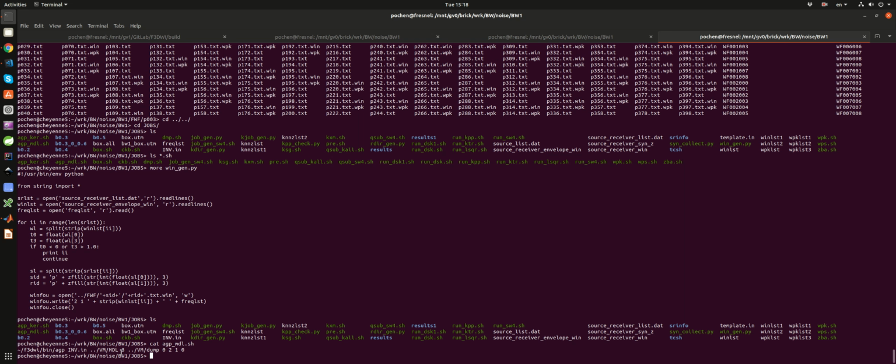If you want to multiply with the cell volume, then you have to change this value to 1. And then 210 is a permutation. The recording grid point has x as the fastest direction and z as the slowest direction, but when I write out this particular dump output, I want to change the ordering of the fast and slow directions.